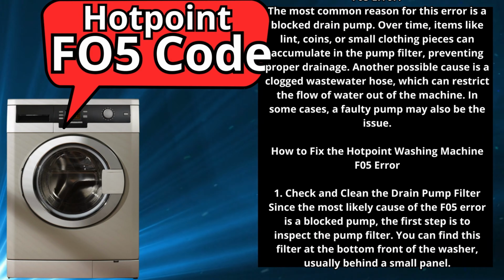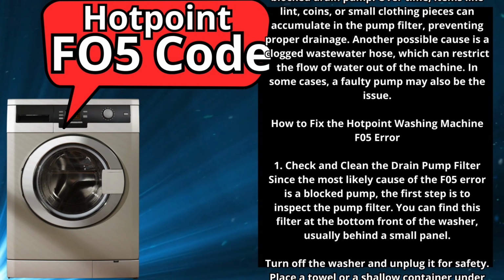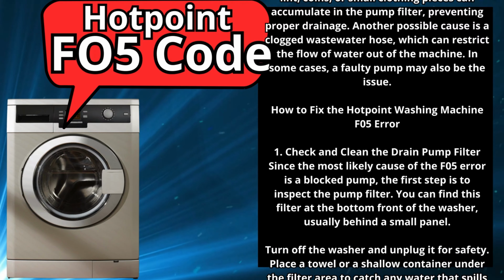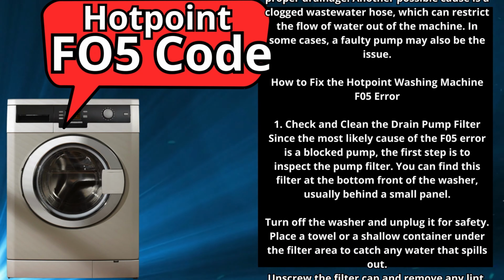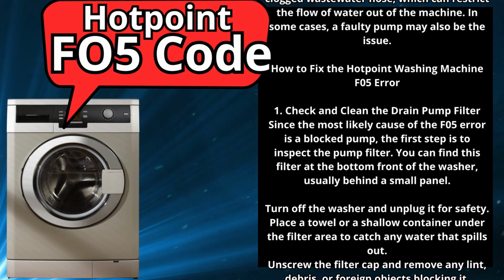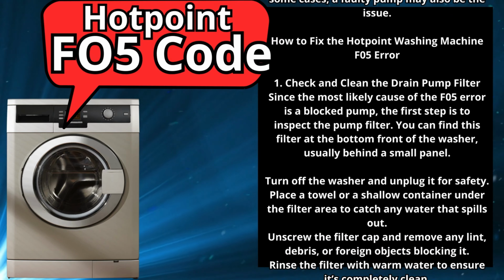How to fix the Hotpoint washing machine F05 error. 1. Check and clean the drain pump filter. Since the most likely cause of the F05 error is a blocked pump, the first step is to inspect the pump filter. You can find this filter at the bottom front of the washer, usually behind a small panel.